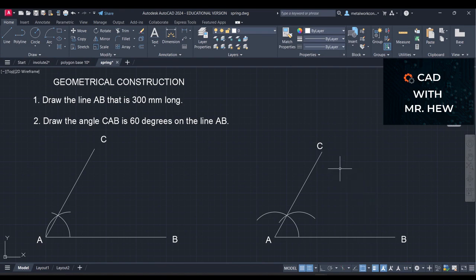How can I prove to you that it is an accurate geometrical construction? Can you guess? Pause the video and then come back. All right, so here I've labeled the diagram for completeness. So D, the first step, you would open your geometry set compass to any radius that is convenient. So you couldn't open it to 5 mm because the radius would be too small. Understand? So you would open your compass to any convenient radius, maybe if the line is 200, then 40 mm is a good radius. But 20 mm could work too.